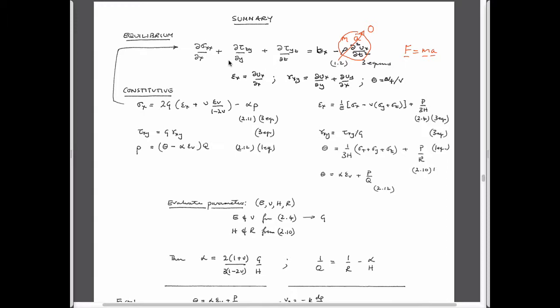So we made the point before that the reason finite element codes all look the same and can solve flow problems and transport problems and mechanics problems is that they all do these four things together. They have a conservation equation: conservation of momentum for solid mechanics, or Navier-Stokes, conservation of mass for Darcy flow, fluid mass, conservation of solute mass for Fickian diffusion, or conservation of energy for thermal problems.